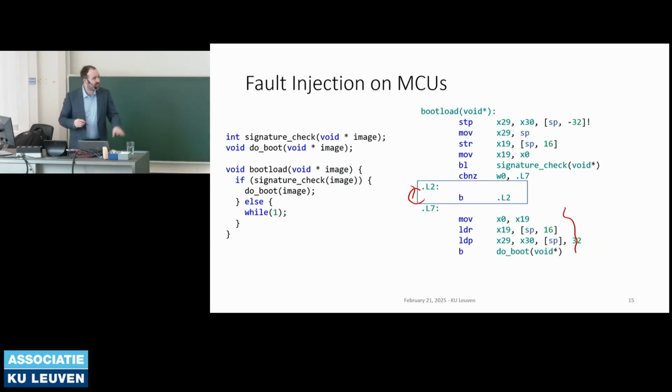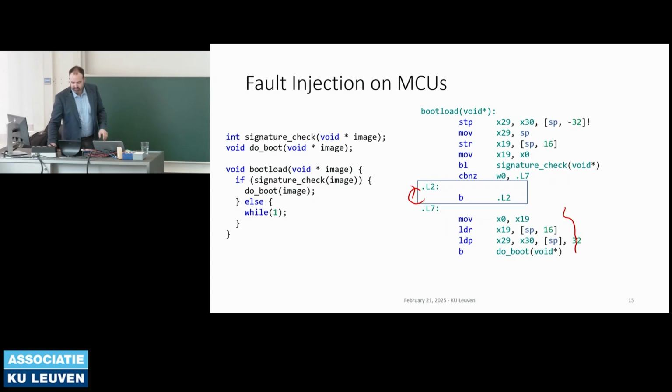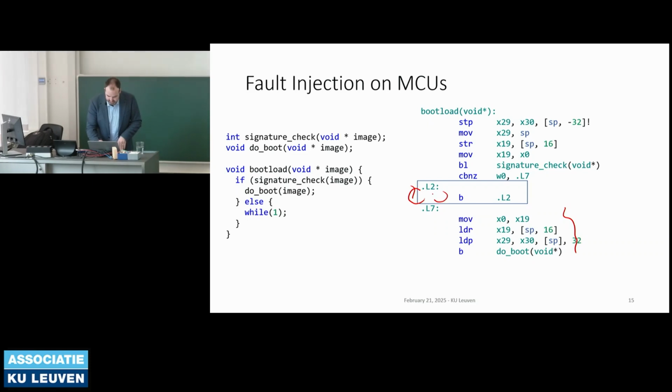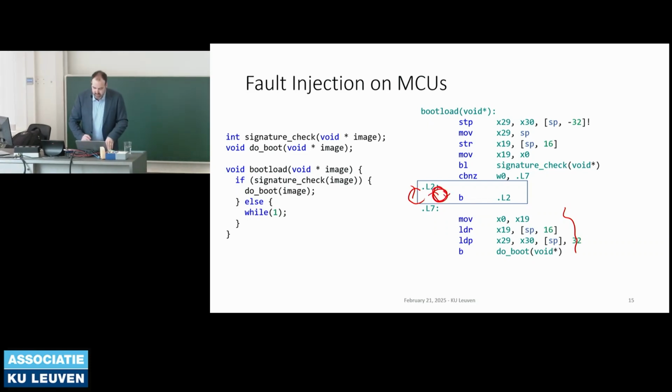The point with this loop is that I could perform fault injection with my little handheld EMFI tool, because I don't need timing anymore. There's no timing requirement. The device is stuck in this loop for a while. It's stuck in that loop until it resets or I glitch it. So I might want to change my code flow so that it doesn't do that. I could go further and make this more fault injection resistant code, but even without caring a whole lot, I've realized that there could be an issue.